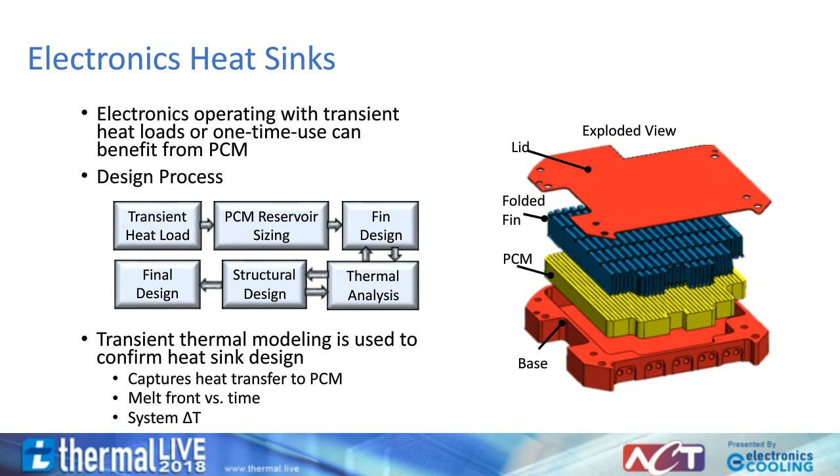There is then the iterative design sequence, reviewing fin design and overall structural analysis that ultimately results in the final design. This transient thermal modeling will confirm the heat transfer to and from the PCM, identify the location of the PCM melt front over time to ensure adequate PCM is present to handle the full transient load, and the overall system delta T to make sure the device is not overheating.